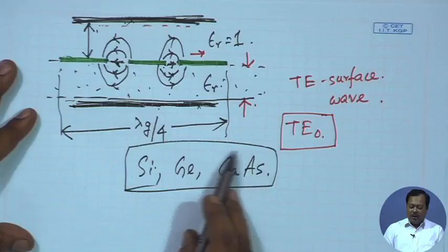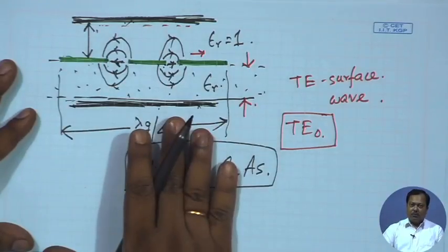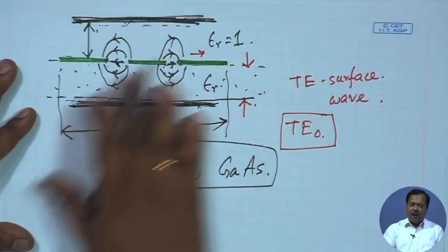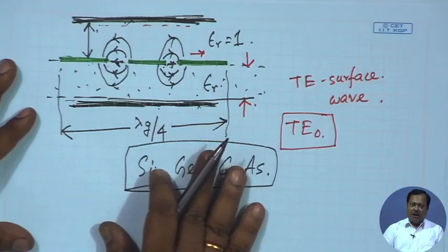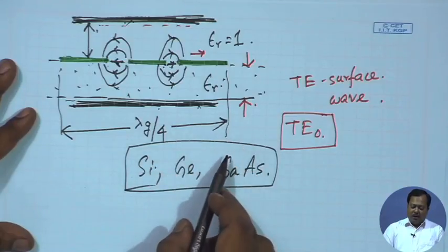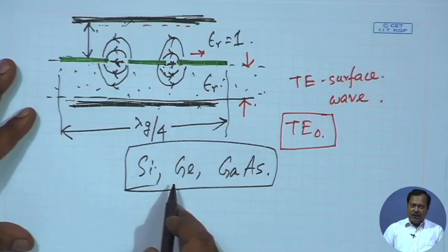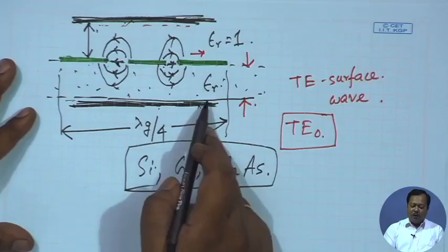For example, gallium arsenide fabrication starts with backside metallization. Silicon germanium does not have any backplane metallization. It starts with bulk P type or N type material. So, in PCB form using laminates, usually we don't use open CPW line like this.